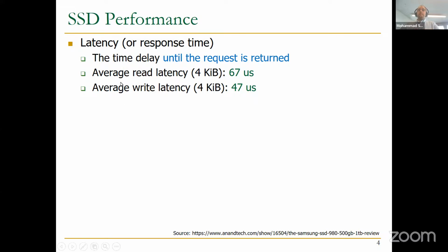And the reason is that whenever you want to do a write operation inside an SSD, normally we write into the DRAM buffer. Then the SSD just sends the acknowledgement to the host system, and we don't really wait for the actual program happening inside the NAND flash chips.